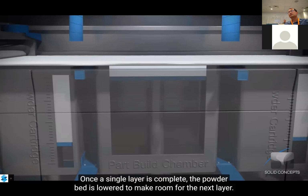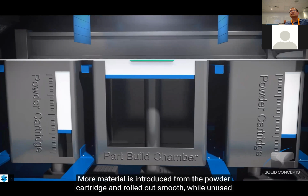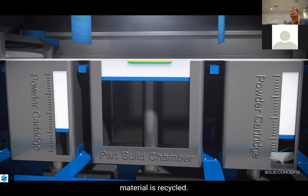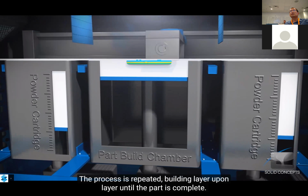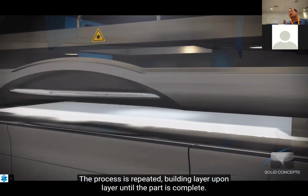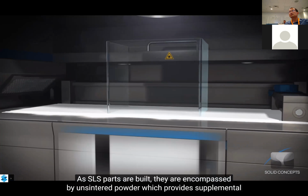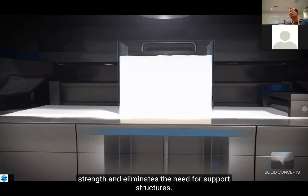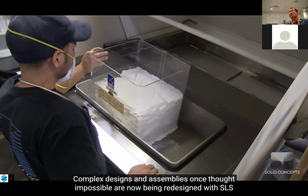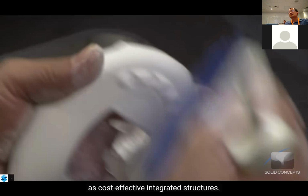Once a single layer is complete, the powder bed is lowered to make room for the next layer. More material is introduced from the powder cartridge and rolled out smooth, while unused material is recycled. The process is repeated, building layer upon layer until the part is complete. As SLS parts are built, they are encompassed by unsintered powder, which provides supplemental strength and eliminates the need for support structures. Complex designs and assemblies, once thought impossible, are now being redesigned with SLS as cost-effective integrated structures.